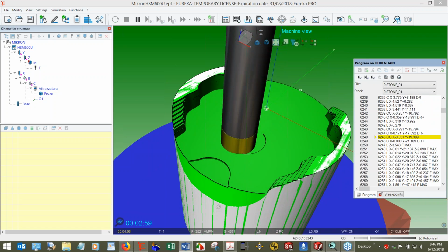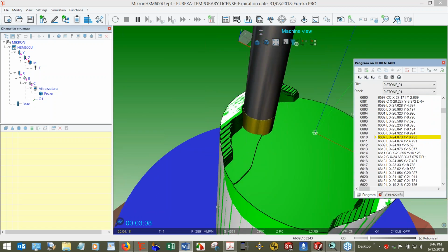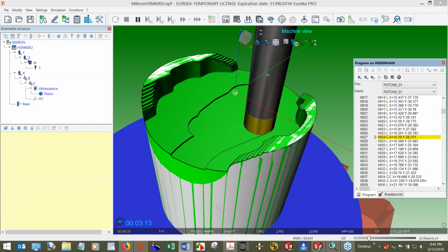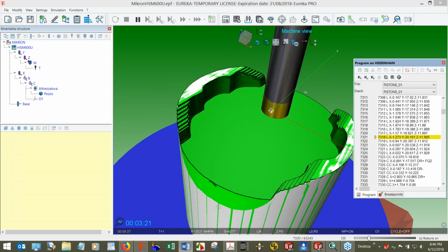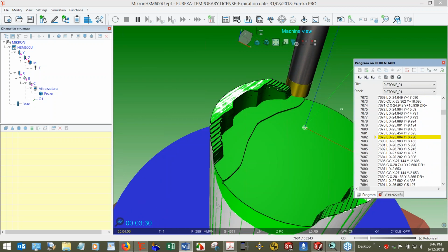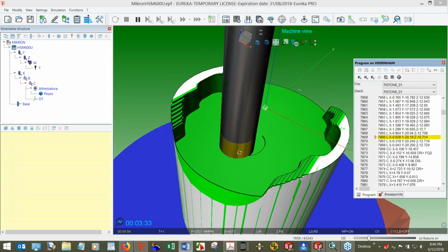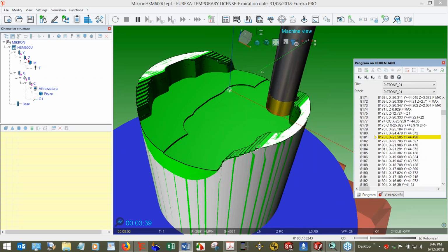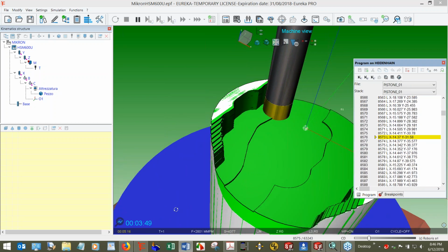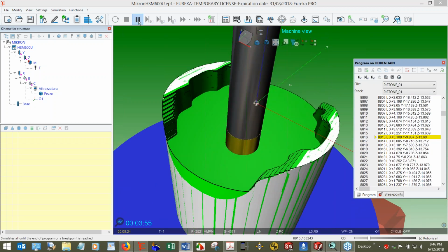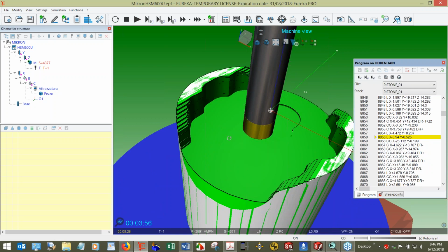And that's not even being overly aggressive, just mildly saying a 20% increase of your cutting data. It's maintaining the chip load and everything else. It's not just a 20% increase. It's looking at the width of cut all along the way and the depth of cut. There's a whole lot of stuff you can control on it. Okay. Looks very nice.